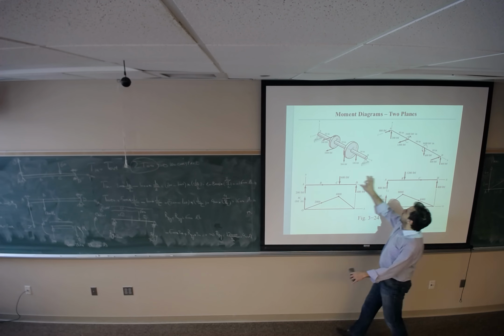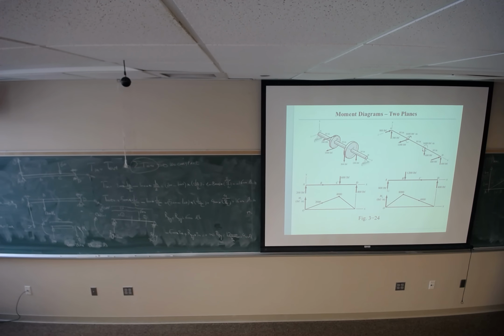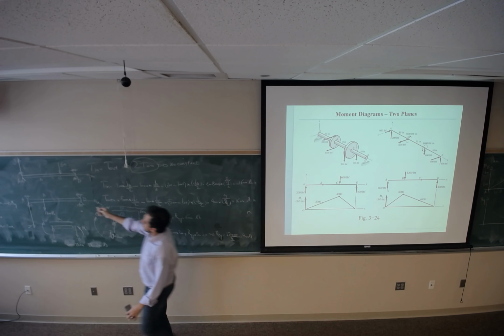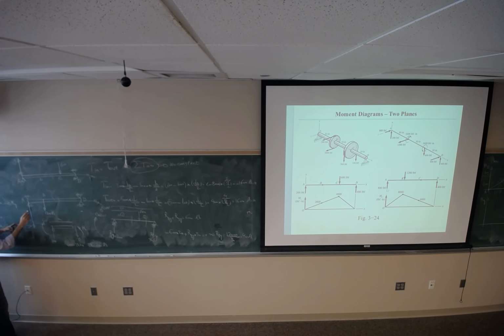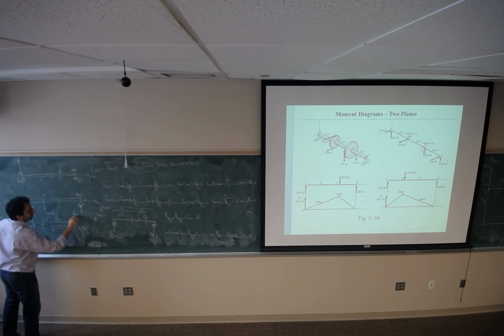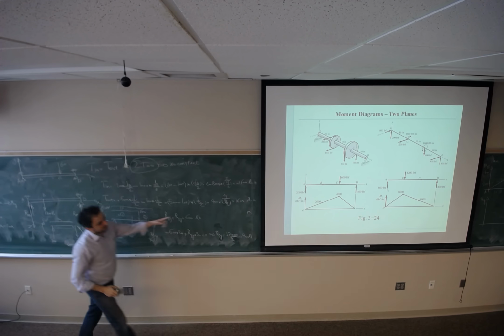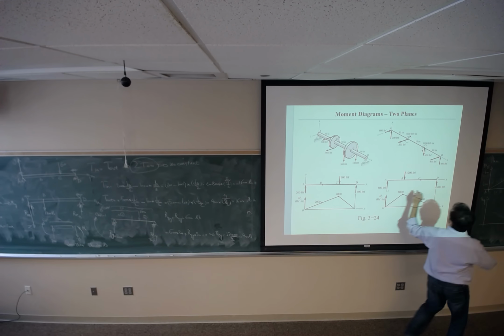Now we look at this plane, plane XZ. Plane XZ is making M with respect to Y. Same logic. I have 200 pounds applied here. What would be the reactions here? R in Z direction at point A. What would be the R in Z direction at point D? If we write the same things, we will get 800 and 400.